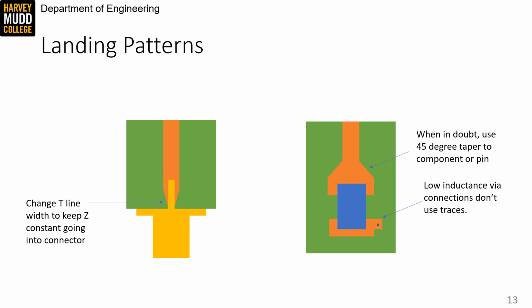So in order to make very low impedance vias, you want to connect them directly to pads, or move them directly onto the pad. I usually opt for connecting directly to the pads on the side like this, because sometimes putting the via in the middle of a pad violates design rules. It can create some weird heat sinking and solder flow properties.